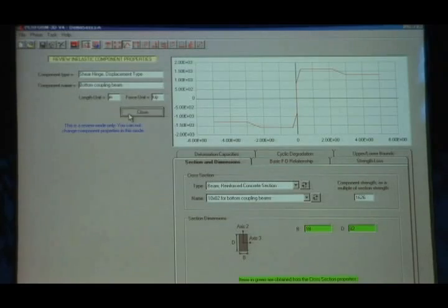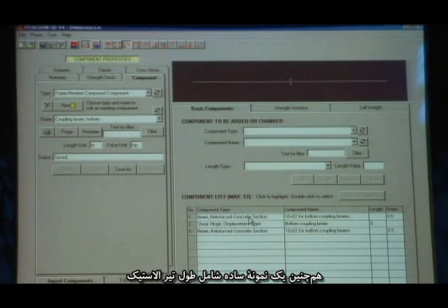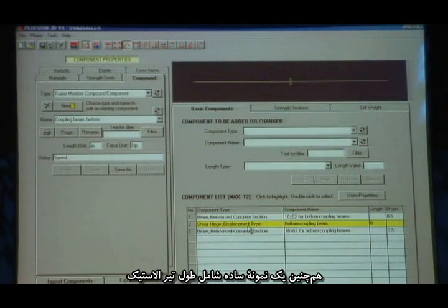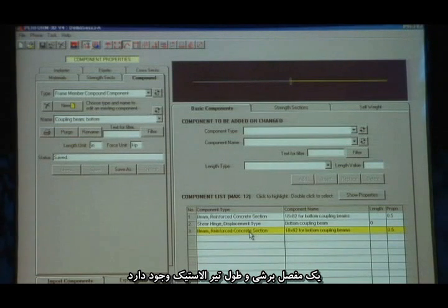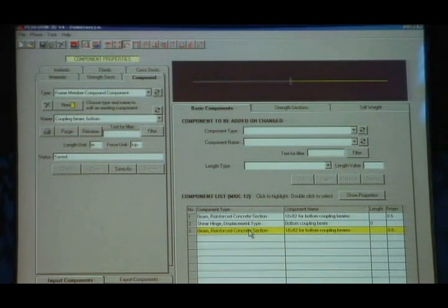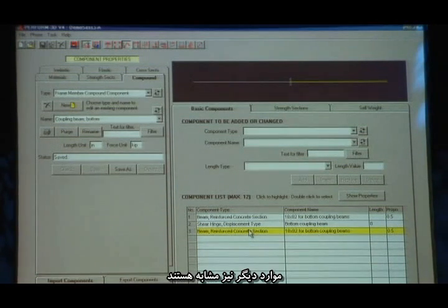So it would be a 0.03, a 3% strain, or a 2.16-inch shear deformation over a 72-inch length. And it was a simple one. It consists of a length of elastic beam, a shear hinge, and a length of elastic beam. And the other ones were all the same, except they had different strengths.